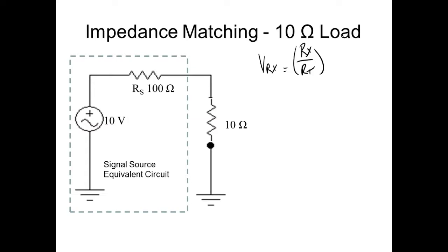Well, most people would go through and do all that calculation. But if you did this right off the bat, I could put any voltage on that circuit, and that resistor would always drop that percentage of that voltage, no matter what the input voltage is. And we call this the voltage divider formula.